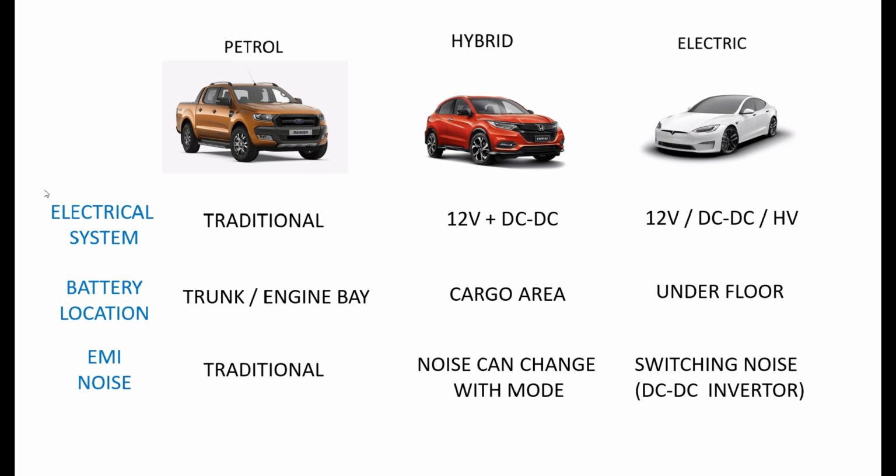It's not huge. And typically the electromagnetic interference, or the electrical noise that you get from the electrical system, is pretty rare. I mean, sometimes you get alternator whine, zzz, when you're pressing on the accelerator, and the alternator winds up, and you get this whine sound coming through the speakers. That's the most common EMI type of noise that you get in traditional cars, right?